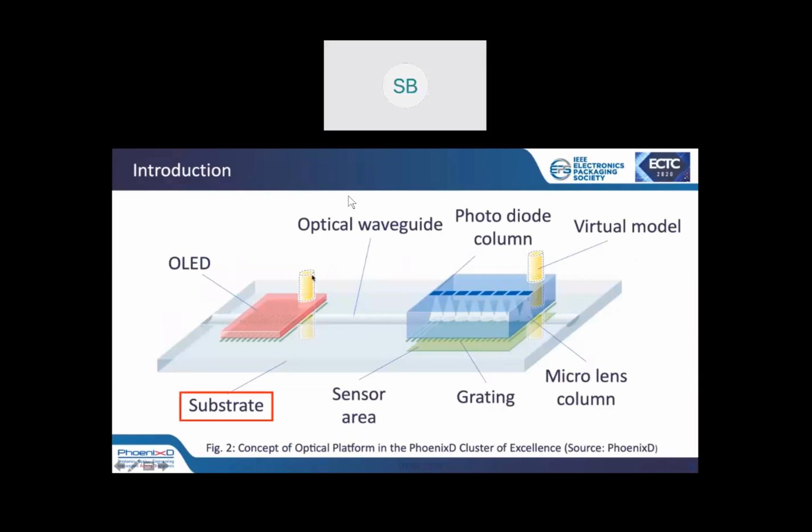For our concept, we use a thermoplast material, which is laser direct structurable. It is a polyether-ether ketone, also called PEEK, supplied by the company Ensinger. This is a material which is also used in terms of MID, mold interconnected devices. The material is highly chemical inert and has a high temperature stability of about 300 degrees Celsius.